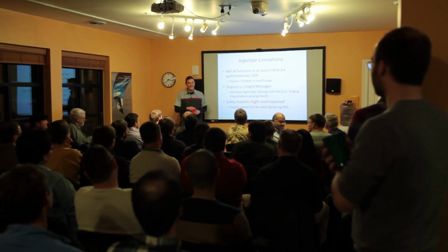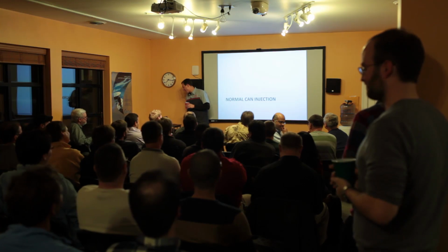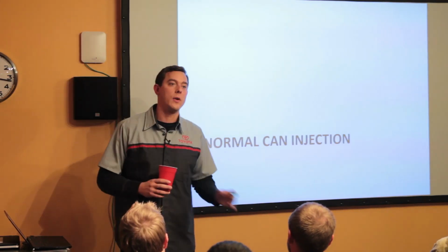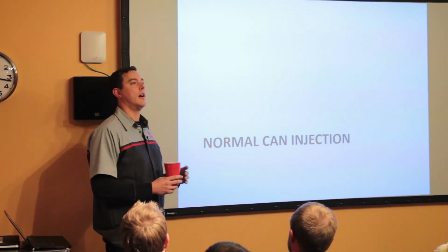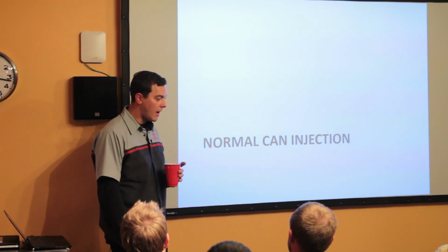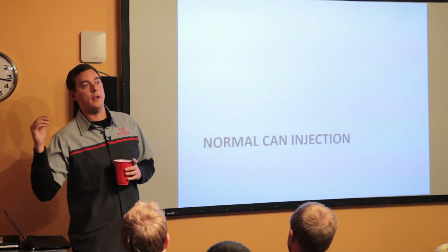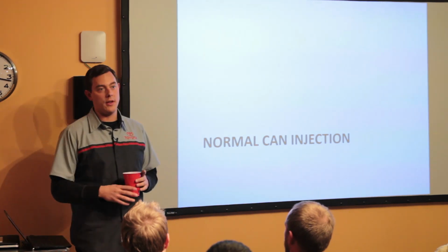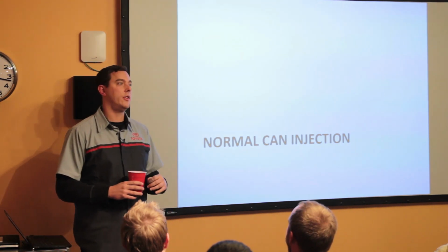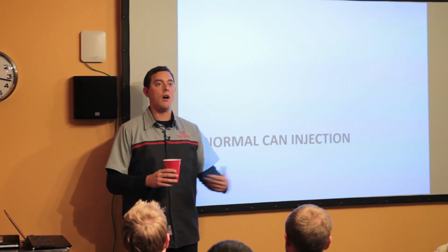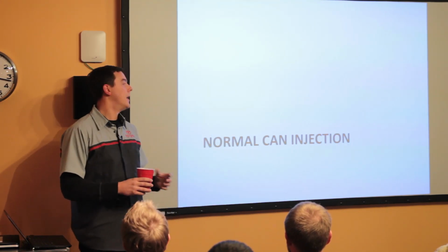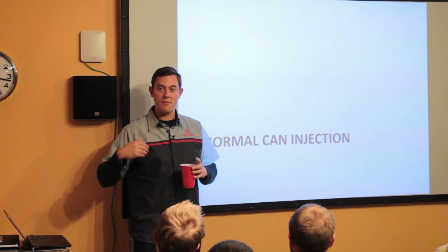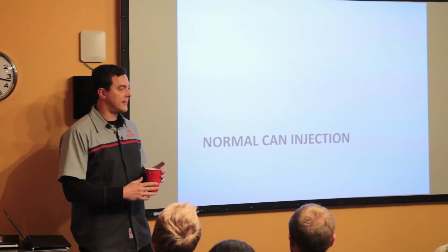Effing magic. All right. So normal CAN injection, when I say normal CAN injection, these are not diagnostic packets. What we did here, as opposed to what the researchers at Washington and California, San Diego did, was we examined messages that actually were naturally occurring on the CAN bus. These were always being spit out. And we just forged them and sent them faster, and we won, and the car did stuff.